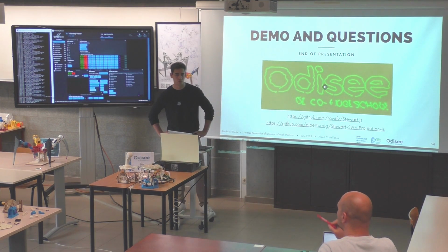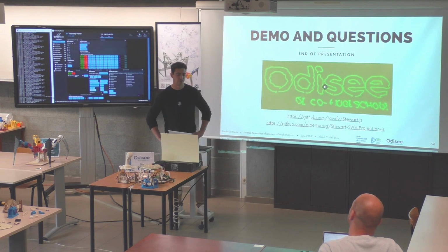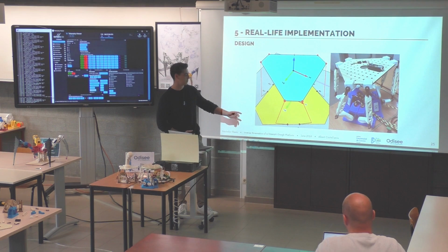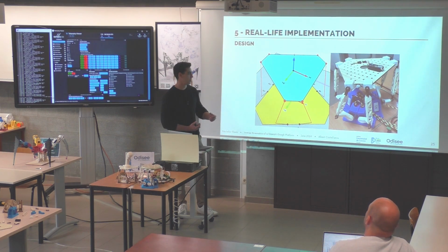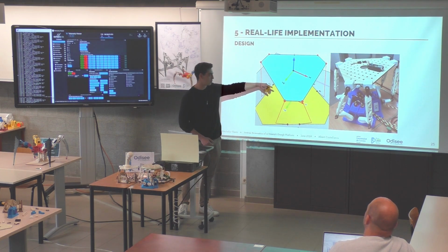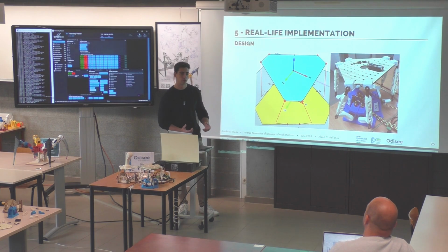The initialization of the platform, how does it work? Basically, there's a function that calculates the position of all the elements of the platform depending on its physical parameters. So I will show you the platform to explain better. You enter all the parameters of the platform beforehand in the code. So you enter the rod length, the horn length, and the radii that compose the platform and the base, and from there the software makes the calculations to know how the platform should look. So that's what we mean when we say that the platform is initializing.